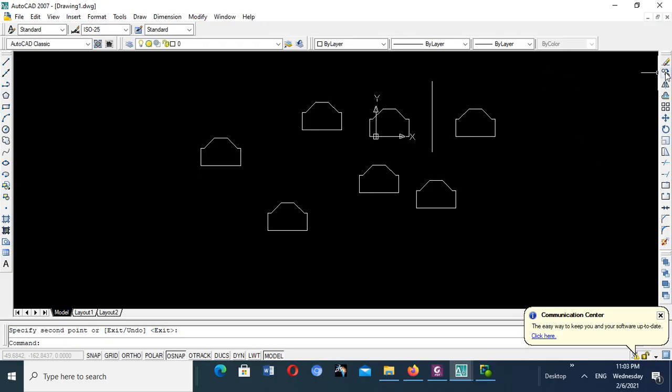So we've learned copy, we've learned mirror, we want to learn offset, right? So let us press offset. We specify offset distance. So we say 100. Enter. Select object to offset. Then this is the object to offset. Select point on side to offset. This is the point on side to offset. Easy, right? And it's very conversational. Some of the things you just go by the conversation.